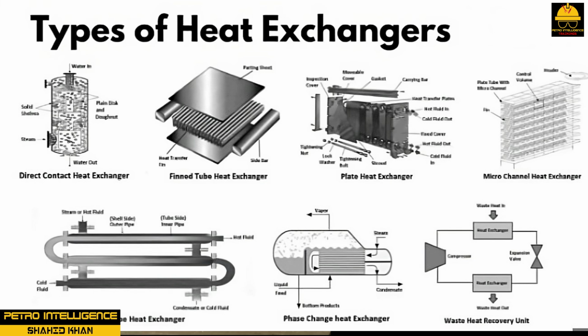The double pipe heat exchanger incorporates a tube within a tube design. It can be found with plain or externally finned tubes. Double pipe heat exchangers are typically used in series flow operations in high pressure applications up to 500 psig shell side and 5000 psig tube side.